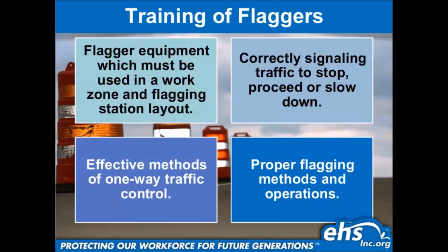All right. Training of flaggers. Flaggers have to be trained on the equipment which must be used and how the station has to be laid out. The signals, guys: how to tell traffic to stop, proceed, or slow down. How to control one side of traffic at the very least. Proper flagging methods and operations.